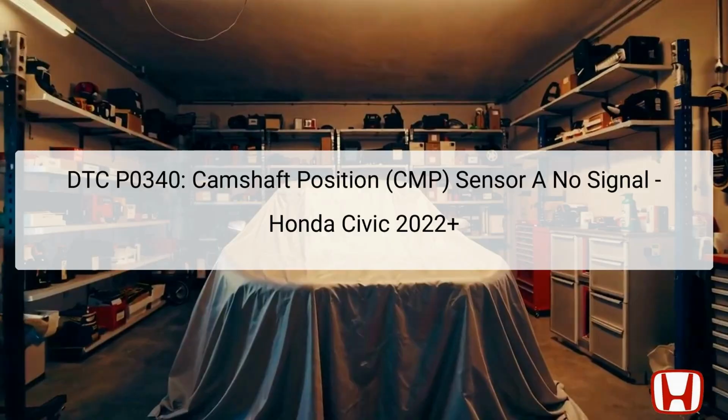The P0340 DTC code indicates a problem with the Camshaft Position Sensor A, which is essential for accurate timing of engine operations. This sensor detects the position of the camshaft, allowing the Powertrain Control Module, PCM, to adjust fuel injection and ignition timing accordingly. When the PCM doesn't receive a pulse signal from the CMP sensor A, it triggers this error code. Its location is typically near the engine's camshaft, allowing it to monitor the position effectively.